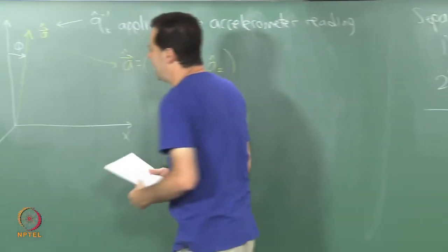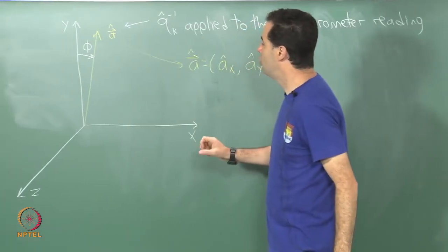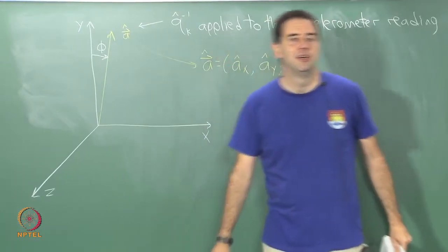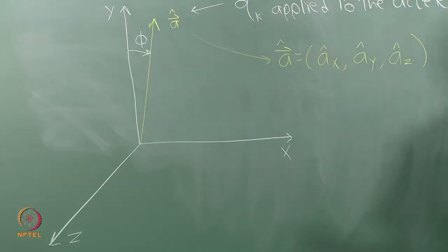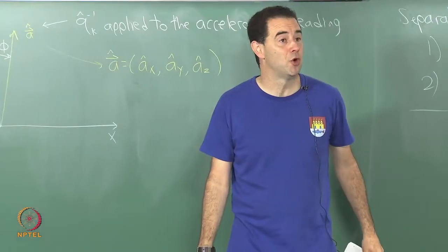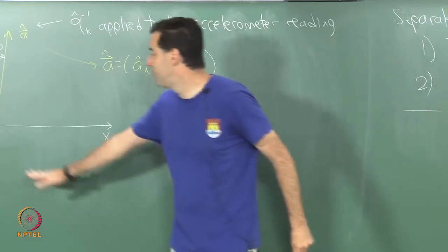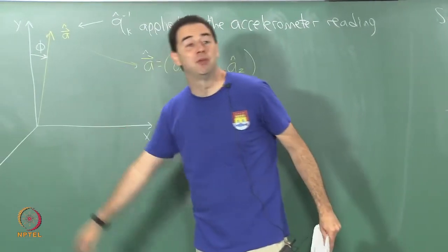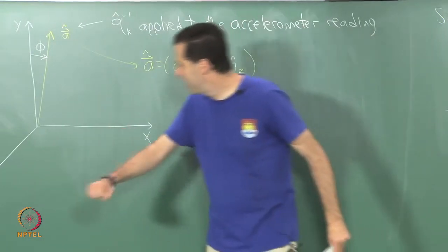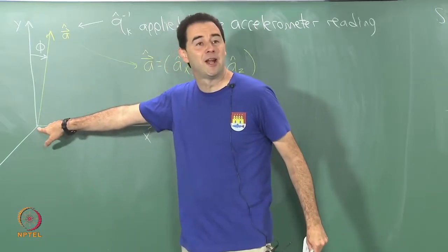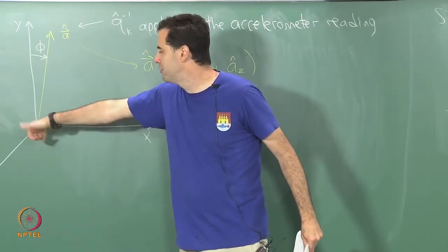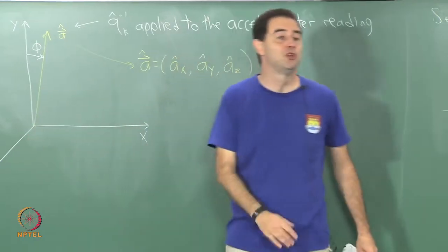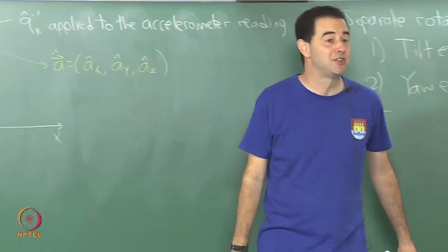And now what I would like to do is perform a rotation that does not cause any yaw to change. I just want to change pitches and rolls. In order to do that, I want to find an axis in the xz plane. I always do rotations about axes that go through the origin, so just imagine that I need some axis that goes through the origin. It also lies entirely in the xz plane.